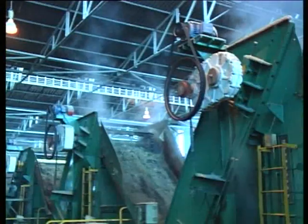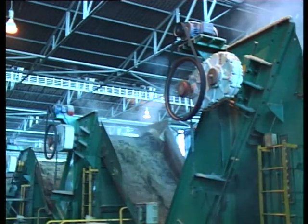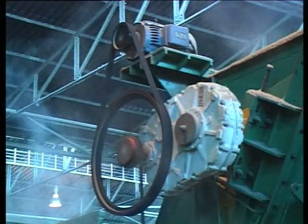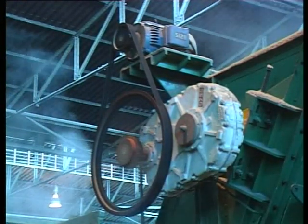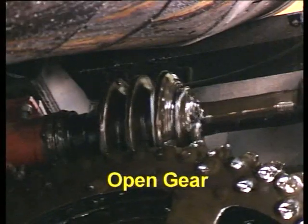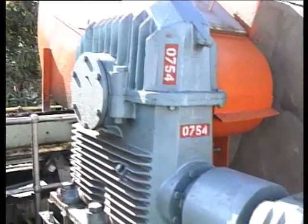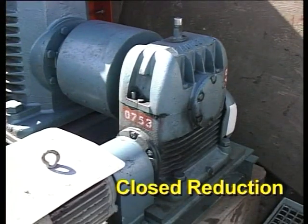Many processing operations are driven via a combination of methods, often through drive belts and then into a geared reduction unit. Here, the geared unit supplies a partial reduction between the power source and the driven machinery. Sometimes a reduction process is accomplished using open gears, as we see here. More commonly, you will see reduction units that are fully encased. We refer to these as closed reductions.